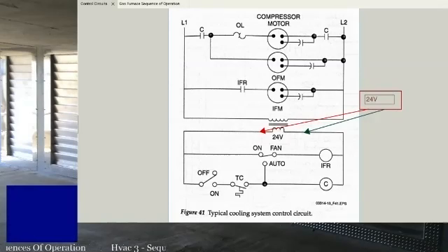If you've got an electronic thermostat, it's probably got some kind of compressor protection in there. So if it's run in the last couple minutes, you're going to have a 3 to 5 minute timer generally. Especially if it's a heat pump, that timer could be 10 minutes because there's one in the circuit board and one in the thermostat. If you can disable the one in the thermostat, if it's got one built in the outdoor unit, that's not a bad idea. But you're going to have a few minute delay.